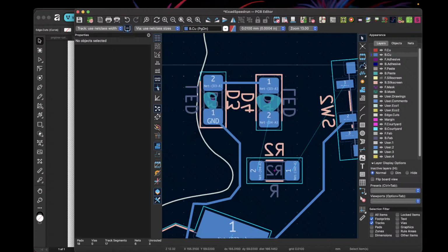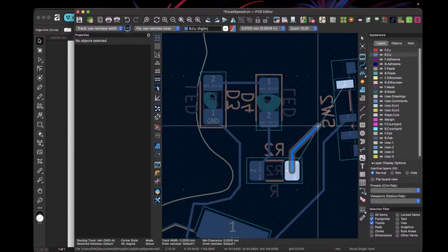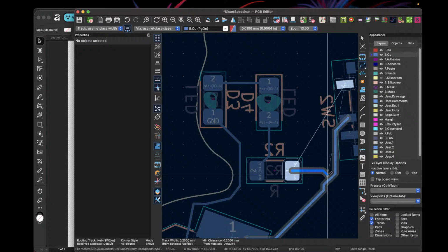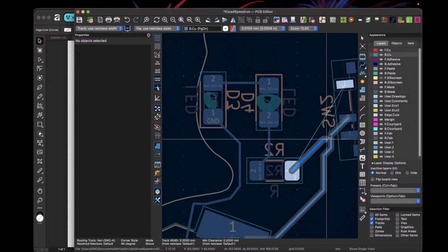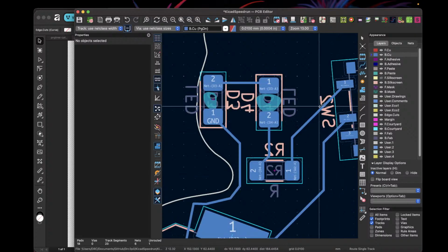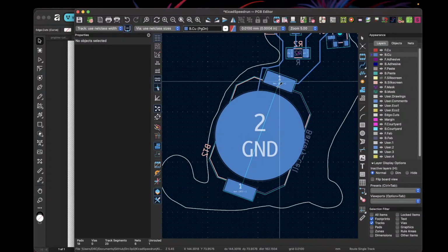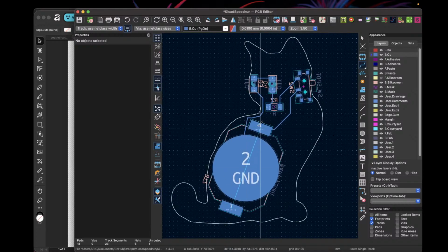So that, we're going to highlight and drop that there and drop that one there. And see, it'll also push tracks out of the way. So if you have a bunch of traces on your board, it makes it a lot easier to lay stuff out. So then throw that there. And this really wants for these to be connected, even though this is a giant piece of metal that connects it over it. It doesn't know that. So I'm not actually worried about that.